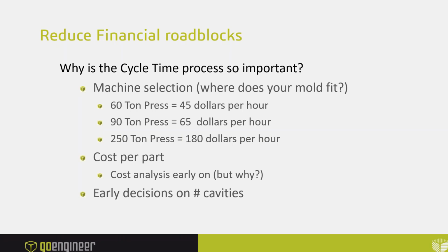And then we add one more factor to that, which is how long it takes the machine to open and close. Now, with older machines, that could be 6 to 8 seconds. On newer machines, it could be 2 to 4 seconds, right? So your cycle time tells you essentially how many parts you can run a minute, or therefore how many parts you can run an hour. And so why do we need to know that information?